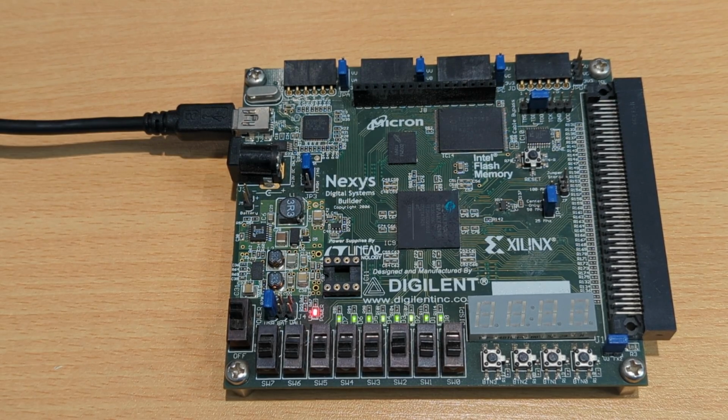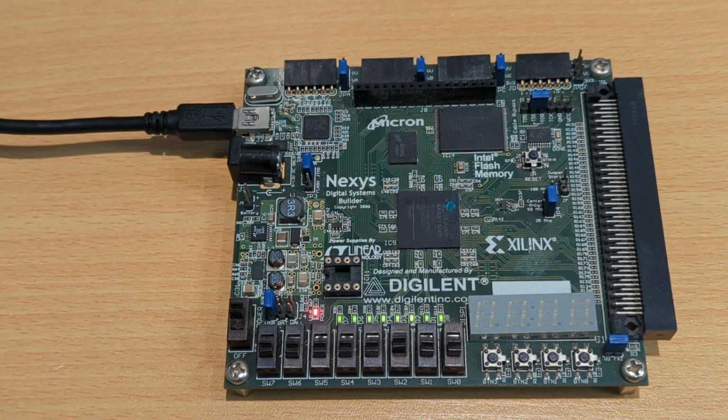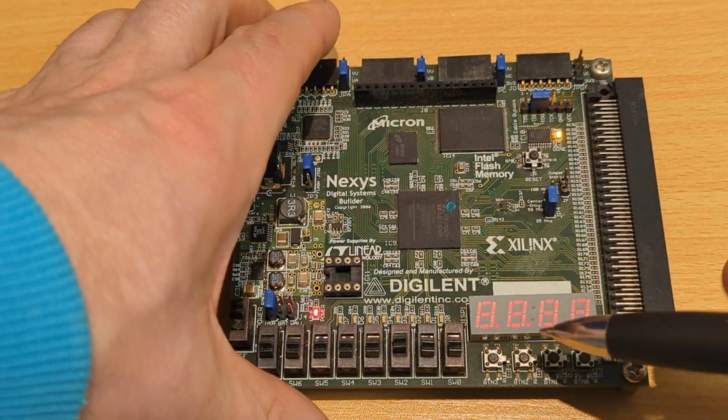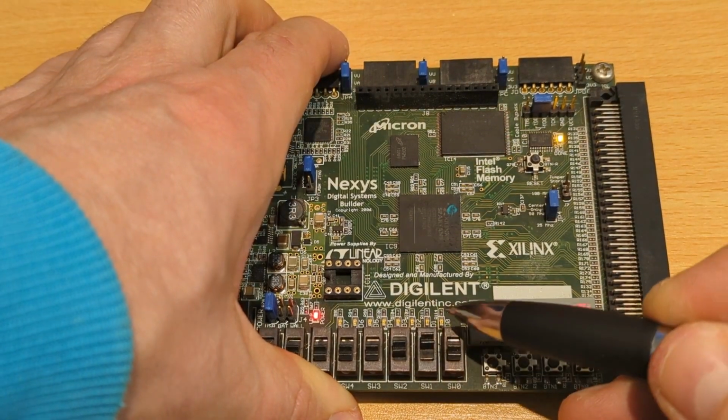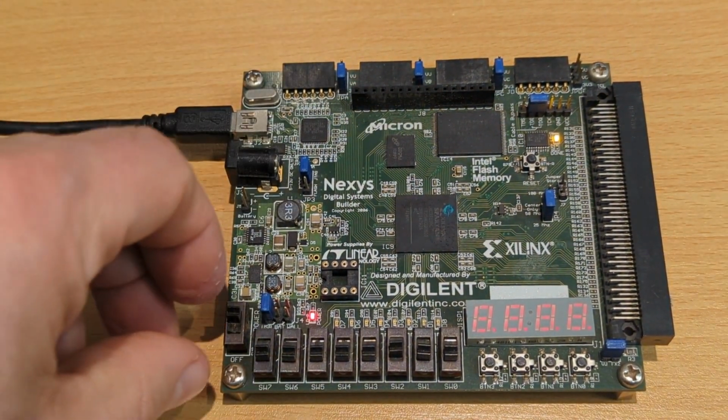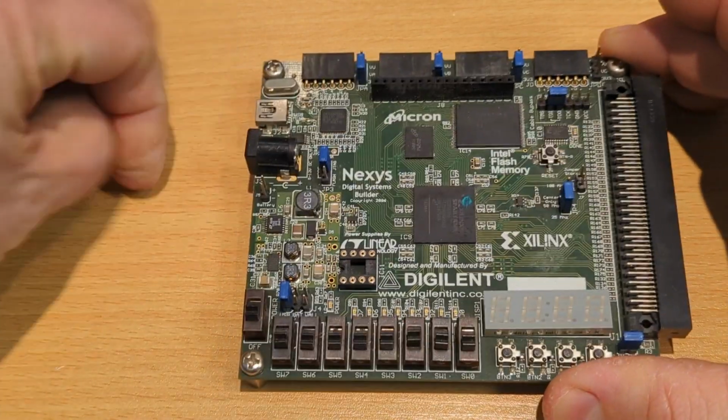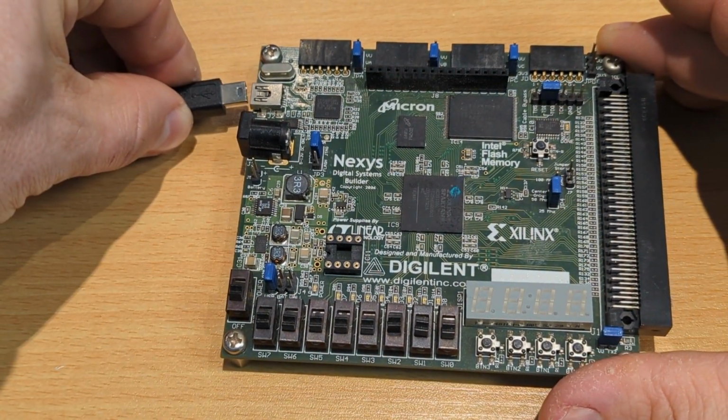So if you want anything of your FPGA design to be kept, you need to program that into the local PROM. Some FPGAs, not this one, have their own memory for storage of the program, so it can be done, but it's very rare. Generally, a little PROM is kept outside. This one has now been programmed by JTAG, so I managed to program it again, but as I said, after power off and keeping JTAG only, that program is going to be lost from the FPGA.